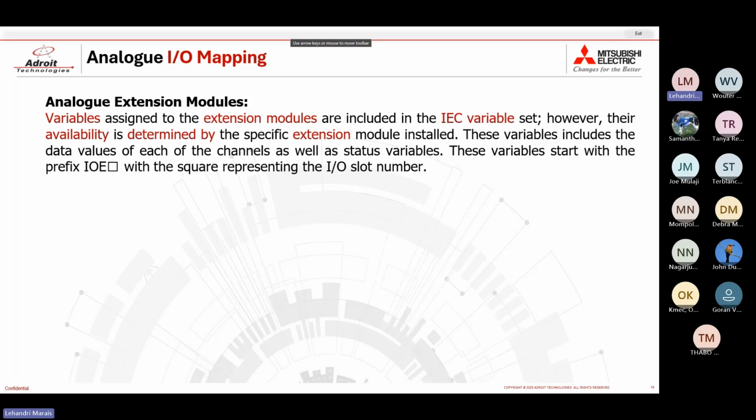So you'd have IO slot 1. So if your analog input or output or analog module is installed on IO slot 1, the prefix will be IOE1, as opposed to if your module is installed in IO slot 2, it will be IOE2.